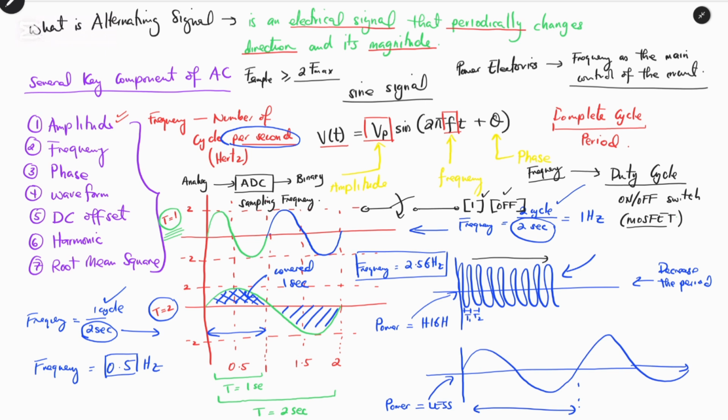Therefore, by choosing a period which is greater and does not follow the Nyquist sampling rule, the signal won't be reconstructed reliably. Therefore, to reconstruct the signal reliably, we must multiply the maximum frequency of the signal by 2. So the speed at which the signal will be sampled will be 2 times the maximum frequency.